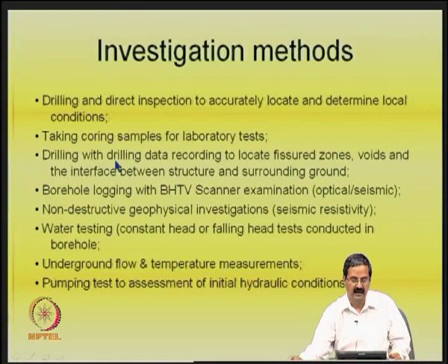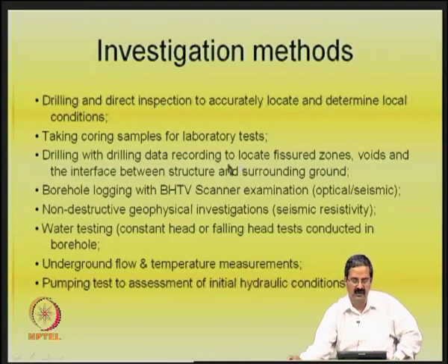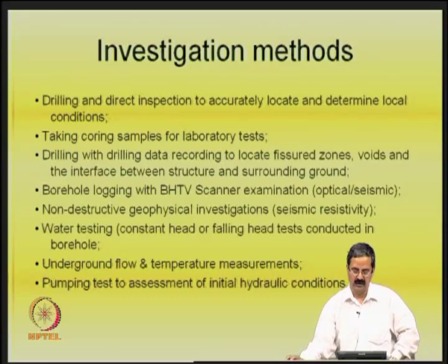Drilling with drilling data to record, simultaneously when you are drilling, you can locate fractured rock zones, voids and the interface between structure and surrounding ground. Sometimes the interface is a critical issue in many of the problems. So, you must be able to get all that information, and we also have what is called borehole logging with borehole TVs and cameras and all that.